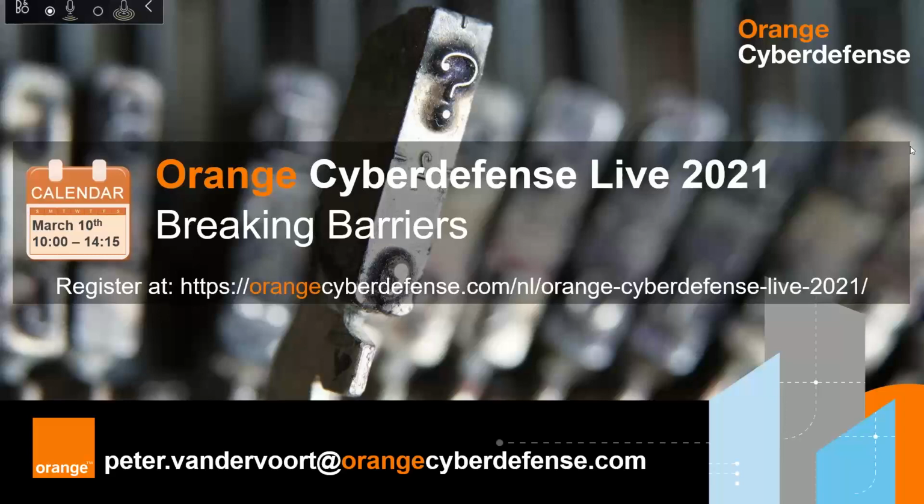Yes, that's a very good question, actually, because when you think about penetration testing, especially from an IT perspective, and you paint that picture onto the OT domain, you can already see PLCs falling over, rebooting, and things like that. But that does not really have to be the case, because penetration testing does not per se mean that you need to scan your PLCs or things like that.